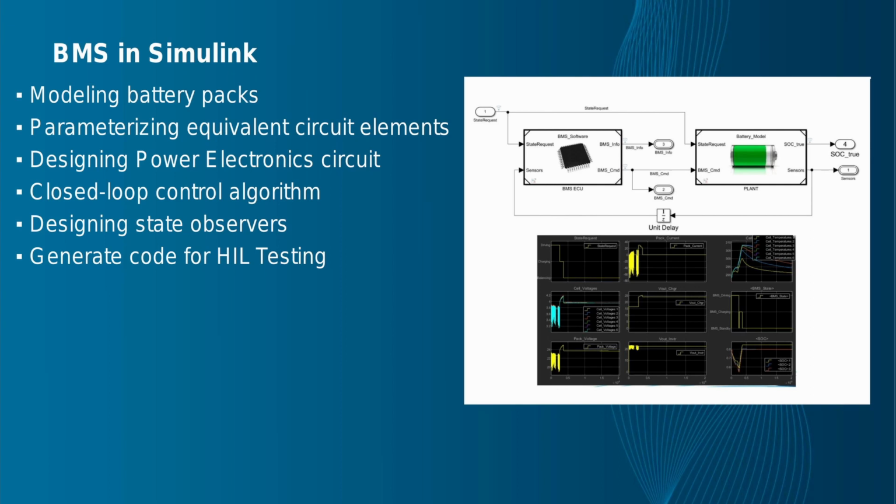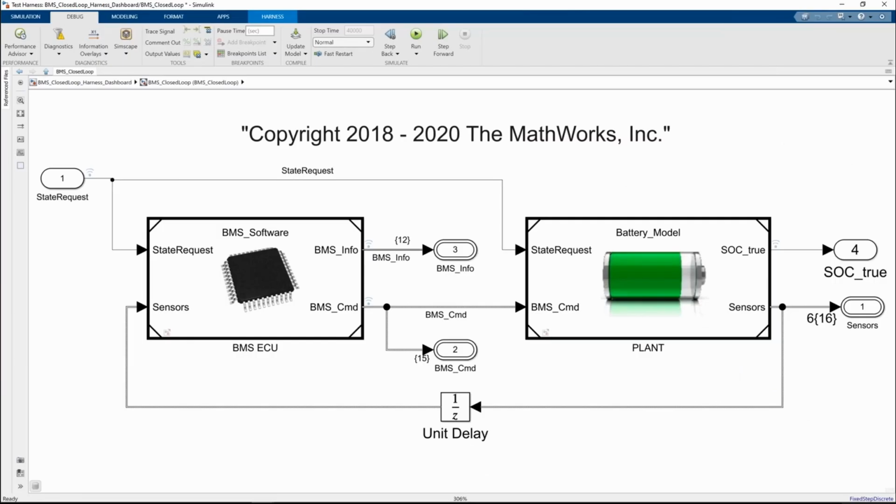You can generate C code from Simulink models to deploy your control algorithms for rapid prototyping of systems or microcontrollers. It generates code from the battery and electronic component models, letting you perform real-time simulation for hardware-in-the-loop testing to validate your BMS before hardware implementation. Later on, we will go through a BMS example model in Simulink to demonstrate the main modeling and control algorithm developing aspects.